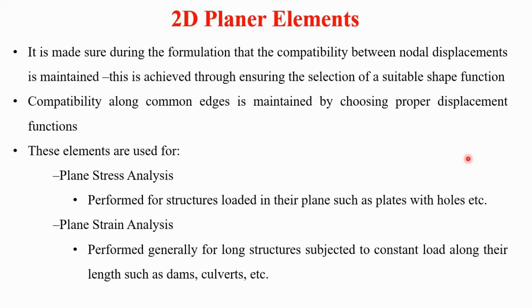Compatibility along common edges is maintained by choosing proper displacement functions. Again, by selecting proper displacement functions we can maintain this compatibility in the 2D planar elements.